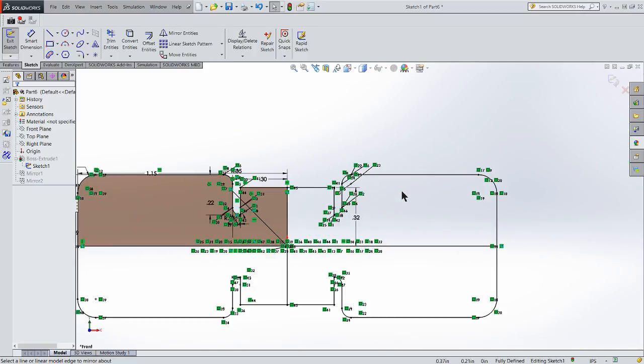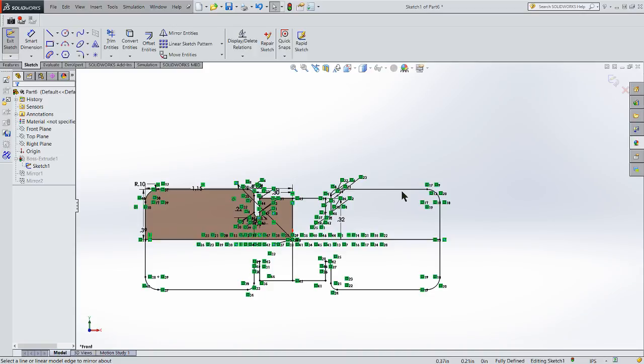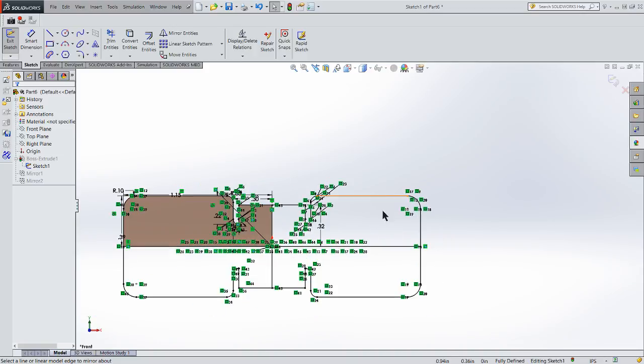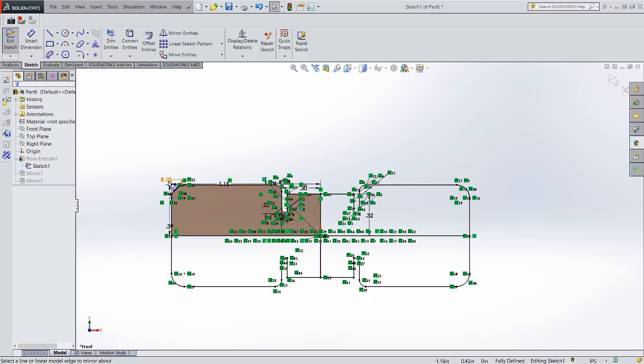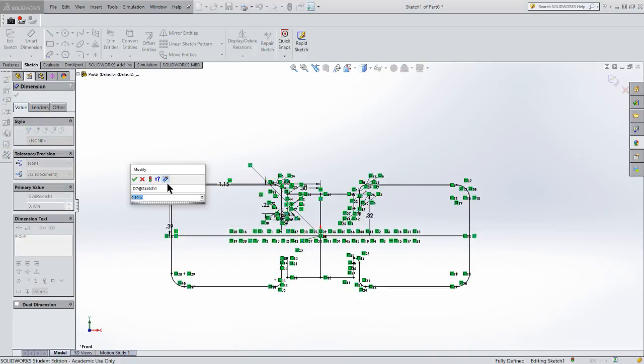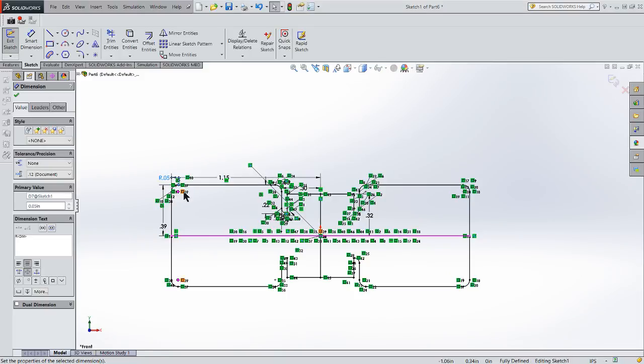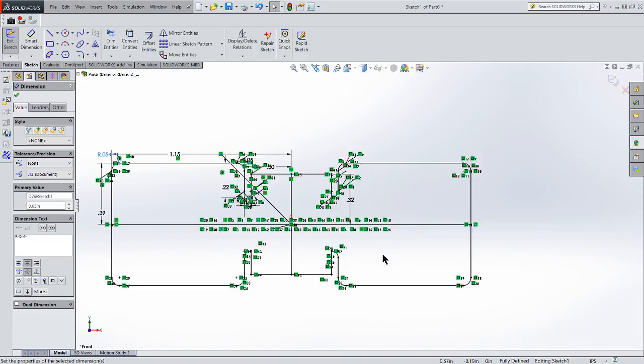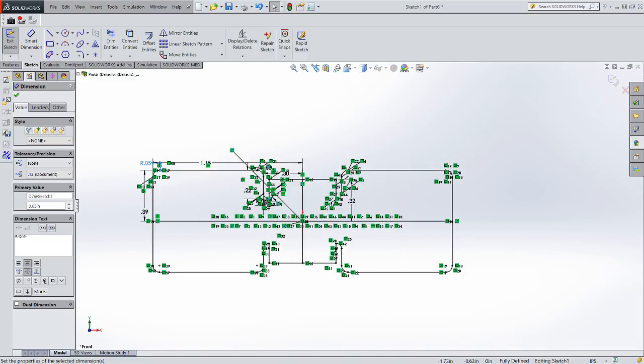Now, you can see the reason we don't really want to do this. You end up with a tremendous amount of dependencies in here that are very easy to break and very easy to disrupt your sketch. If I make a change on my mirrored entity within my sketch, it will transfer into all the mirrored quadrants of my sketch, provided that those relationships are not broken. The problem is maintaining those relationships is sometimes difficult in a real design setting, when your parts will change and they will be modified.